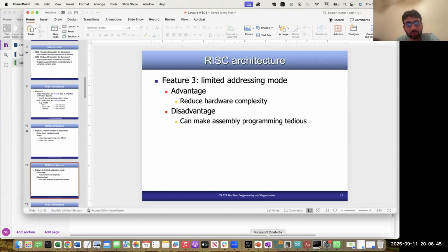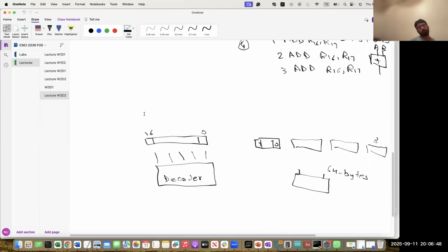So for example, one way is you can directly put the address in a register. Let's say I'm just making up any register, and then you say, okay, read data from this address. Another way is you are putting the address in two registers, R1 and R2. Actually, it is not a plus sign here, but let's say a comma, R1 and R2. And then you are saying use this one as base address and use this as index address, right? So these are different addressing modes, right?